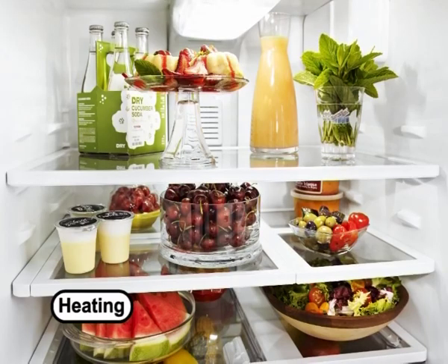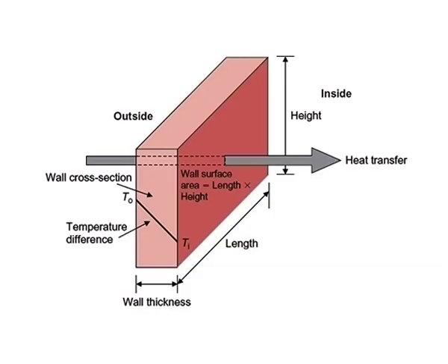Conduction is a mode of heat transfer in which the transfer of energy takes place at molecular level. Note that in conductive mode, there is no physical movement of the object undergoing heat transfer. Conduction is the common mode of heat transfer in heating or cooling of opaque solid materials. Consider the heat transfer across a room wall as depicted in this figure.